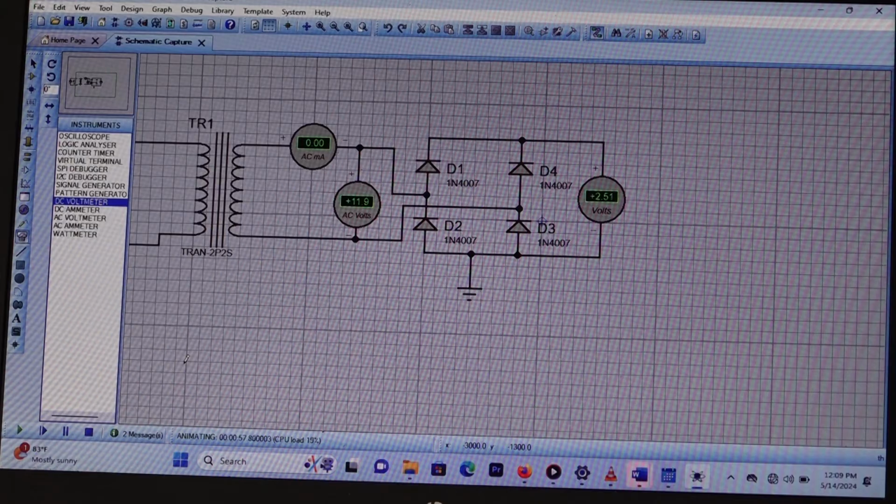Are we together? So the question is, we have a root mean square voltage output, the input voltage to the filter, it's 12 volts, but it's root mean square. I told you that we don't convert root mean square voltage into DC voltage. What we actually have to convert into DC is the maximum or peak voltage.